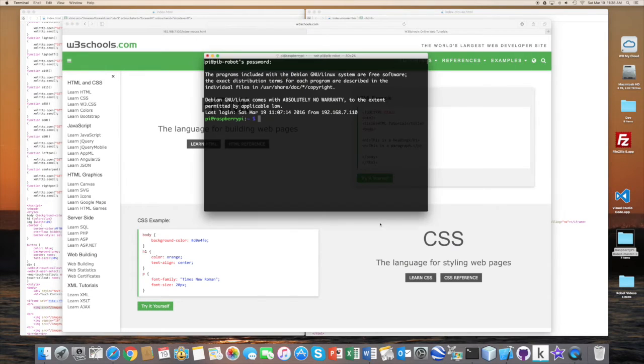Okay, I wanted to go through something with you. There are 5 LEDs that are on at any given time. There are 2 on the Raspberry Pi, there's the camera one, there's a Wi-Fi dongle, the L298N controller has one, and actually our PoE also has a little LED on top of it as well. So I want to turn some of these off. I found out that we can actually turn off 3 of the 5 that we have on the project.